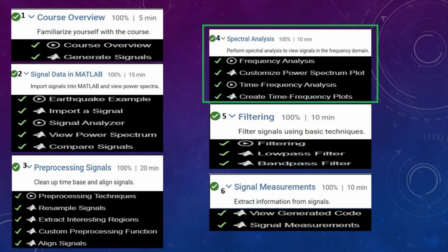C. Time frequency analysis. Power spectrum shows the overall frequency content, but time frequency analysis reveals when these frequencies occur. Methods: spectrogram, based on sine waves. Scaleogram, based on wavelets. Both methods slice signals into blocks to visualize frequency changes over time.